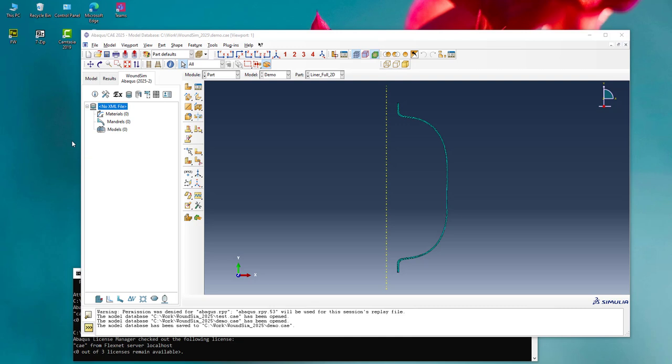It has what we call a WoundSim GUI, a standalone piece of software where we can draw the COPV layup, manage the creation of a finite element model with some default controls, and then manage the running and post-processing of the job separately, from outside of the FEA solver.